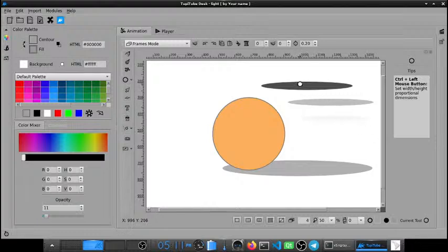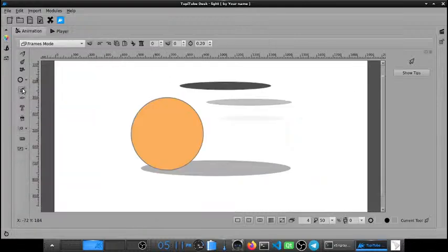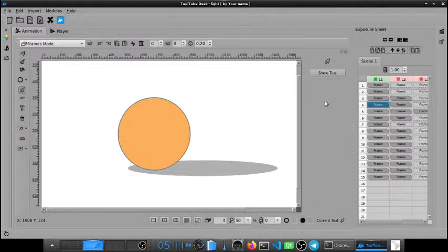Can you see? So depending on the energy of the source of light, you can play with the opacity of the shadow. This is an important thing to have in mind. Okay? So let's keep working on more examples about lighting and shading and scene.